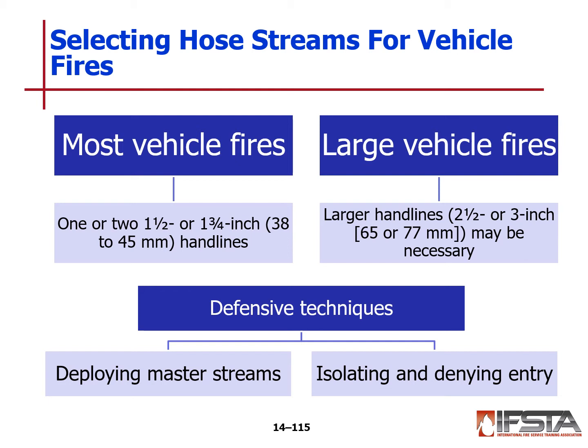I will say that vehicle fires can be one of those fires that seems simple but can embarrass you pretty quick. Sometimes it's hard to get hoods up, as an example, and you get into this business of, I can't get the hood up, we can't get the fire out, fuel lines burn into the plastic or the rubber ones, and then they start dripping fuel out on the ground, and you end up having to ultimately break out the foam pack to get things put out.